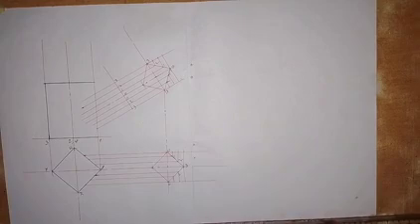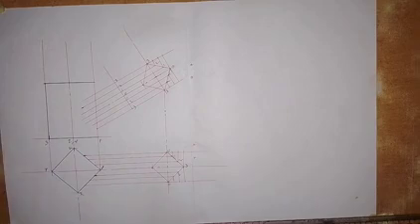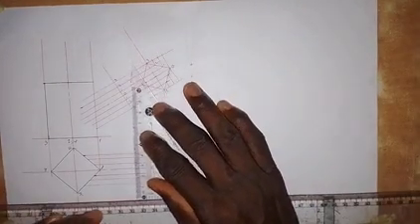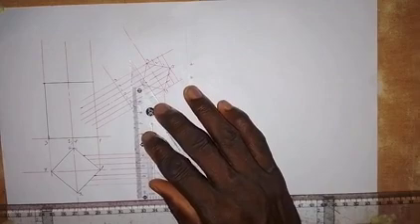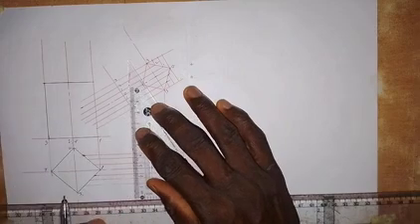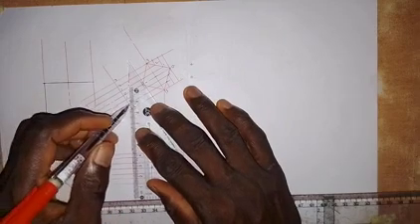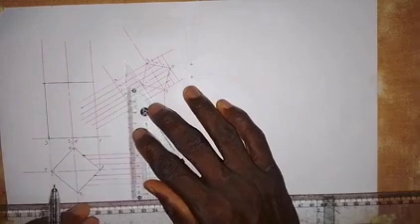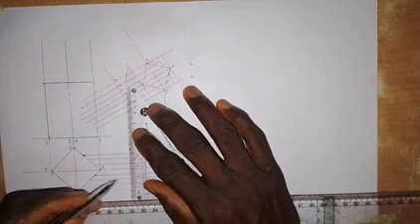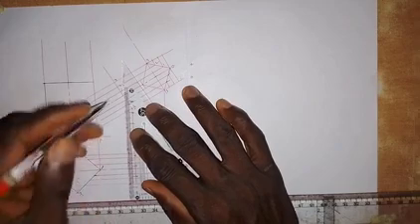So now, having done this, the next thing that we are going to do is, as we are told that we should draw the complete plan and the complete front elevation, you are going to understand how I'm going to do this. Very, very simple. Now we take our set square. So from this point 3, I will draw a vertical line down. Then from point 2, I will draw a vertical line. Then from point 1, I will draw a vertical line. Then from point 0, I will draw a vertical line.